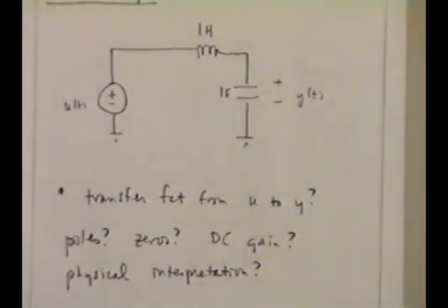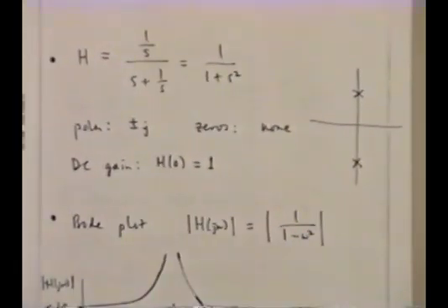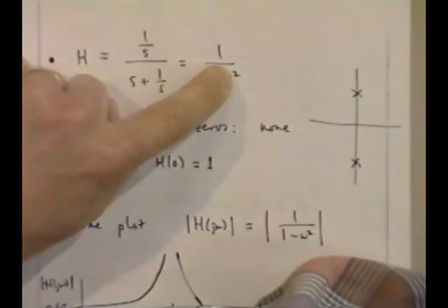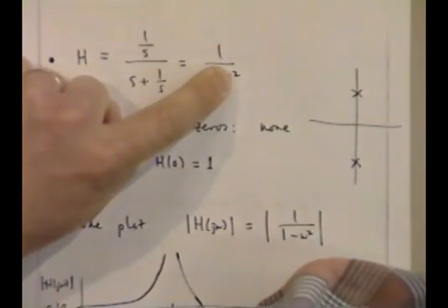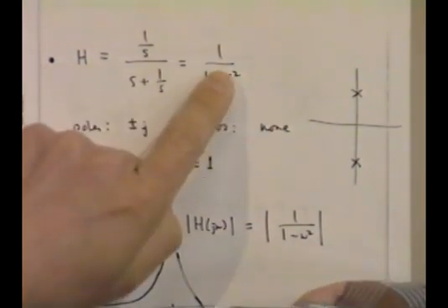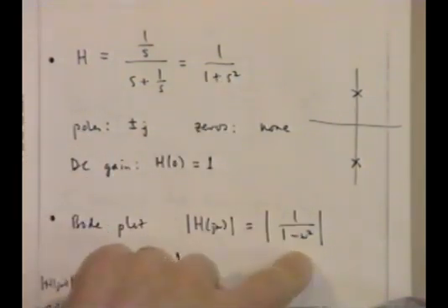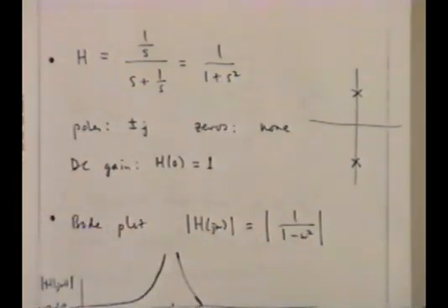And let's see if that's confirmed. How is that confirmed here? Where in the algebra do you see that for large omega, the output of that thing is small squared? Where do you see it? Is it this one? This one? There it is. It's that 2, right? Yeah, it's this 2. It's that exponent, period, that tells you. Or over here, if omega is really large, this thing falls off like 1 over omega squared, right?